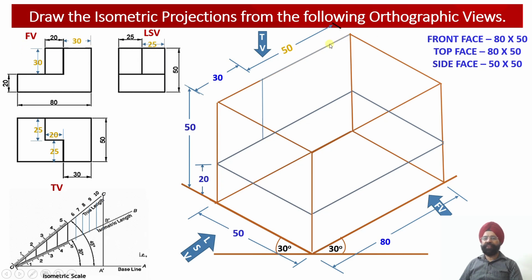So from this point we are moving 50 millimeter towards this end. Now we have to move 30 millimeter down. As we move 30 millimeter down, automatically you see the total dimension was 50, the ring dimension height was 20, so this is automatically 30. But still, for the purpose of clarity, this 30 I have shown again with an orange, lighter color. So this is a lighter color, means you can omit these dimensions, but still I have shown it.